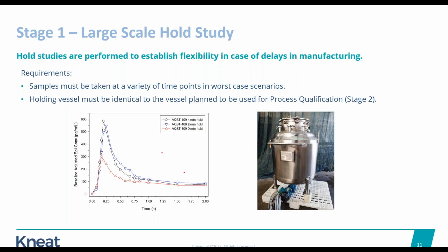This would be performed during the engineering and clinical batches, and then that same study will be performed again during stage 2 to officially validate it. So same type of requirements here, samples must be taken. For these hold studies, they're typically done over a series of days. So for this, samples could be taken every 24 hours, every 12 hours for 3 days. It really depends on what we're looking at here and how many samples we want.